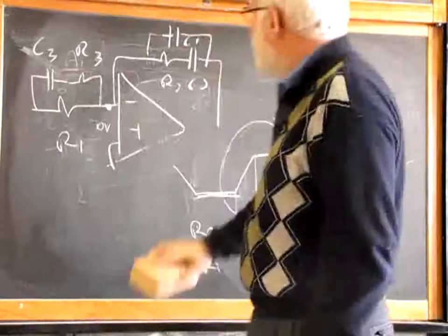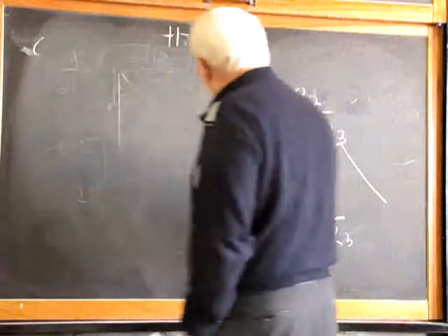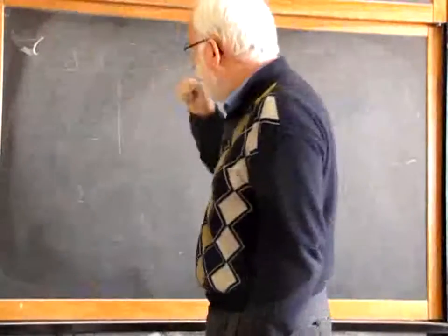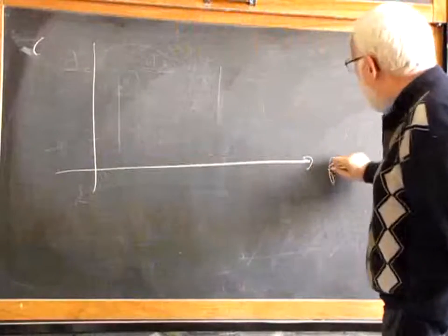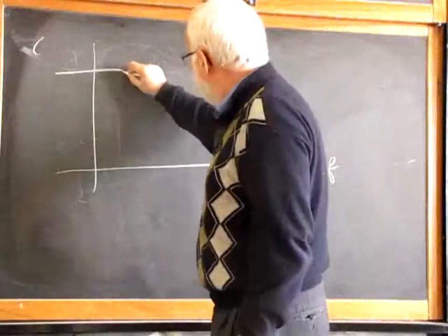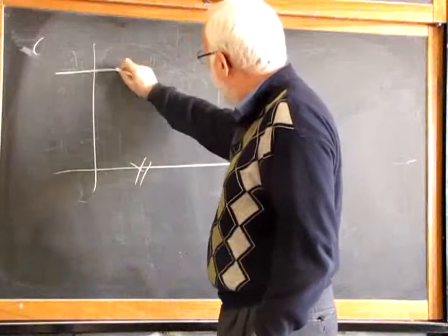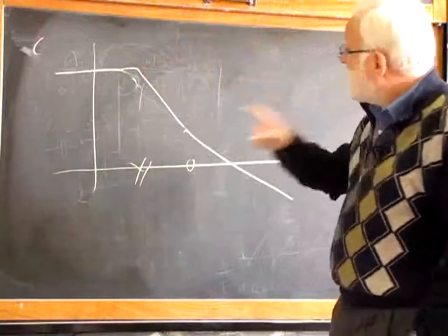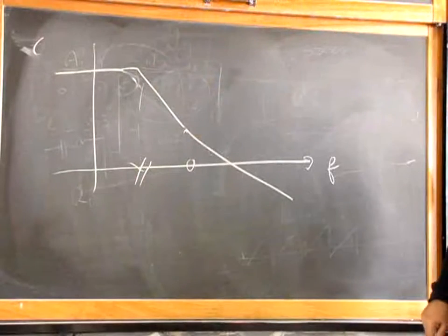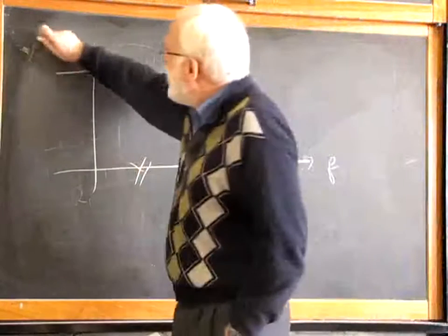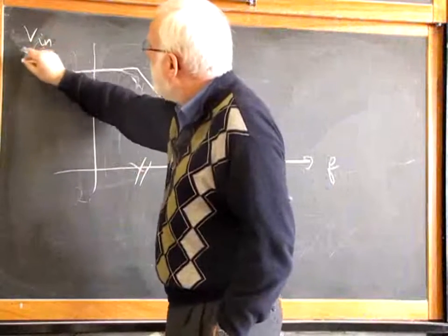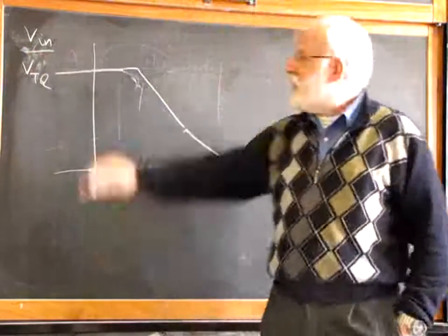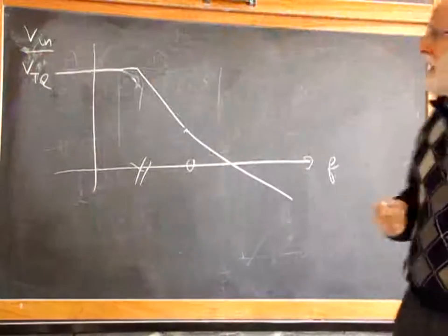Okay? So, we are almost done. We know how to determine all our components. We just need to refresh a little bit how to find the gains. So, this is my transfer function for the buck converter. The DC gain is Vin over V triangle. Vin over V triangle is the DC gain, including the PWM modulator effect.